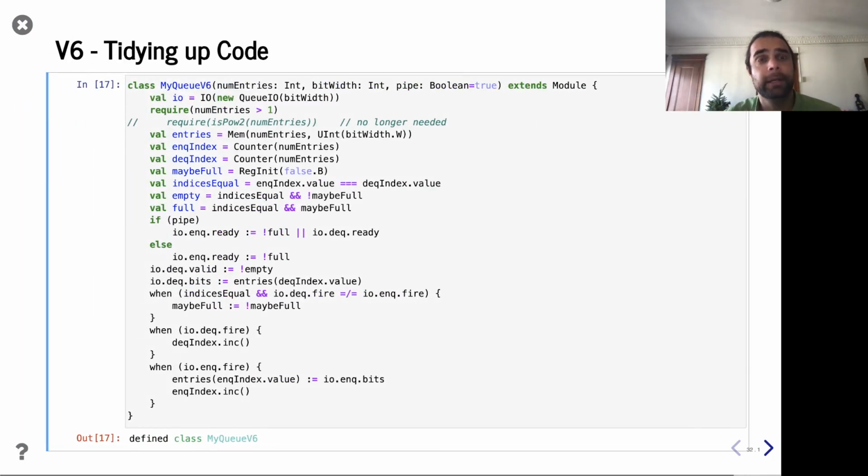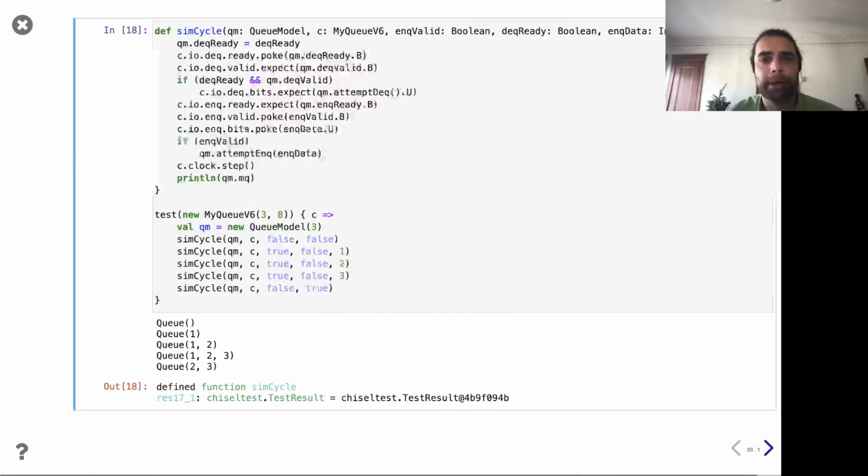the first time, right? And so what we did is this agile incremental approach, right? Start off with a single entry, then went to a shift register, and realized, oh wait, long bubbles. What if we use a priority queue to insert in the right place? And then that was better. And then we went to this memory mode where we have 2 pointers in a circular buffer, right? So we went through 6 versions, incrementally improving it. And along the way, maybe you add a little functionality, maybe you lose a little functionality, sometimes regressions, but in general, it got better, right? Otherwise, you won't make those steps. Even so, you maybe take a trade-off, make this thing better at the cost of something else, but we made progress, right?